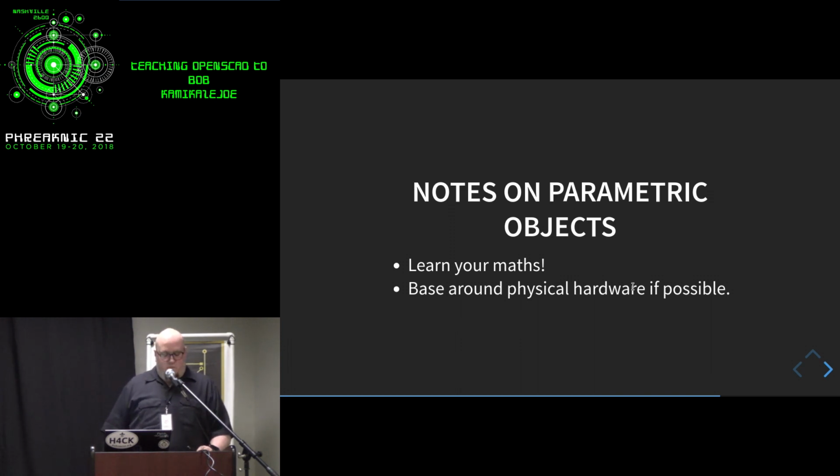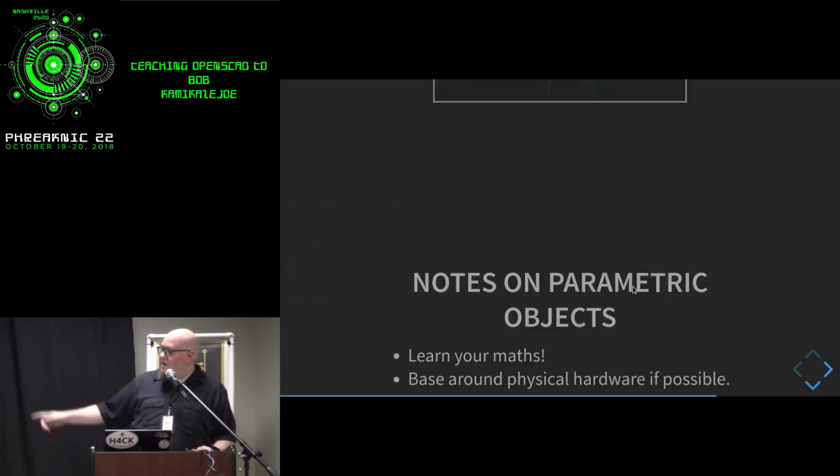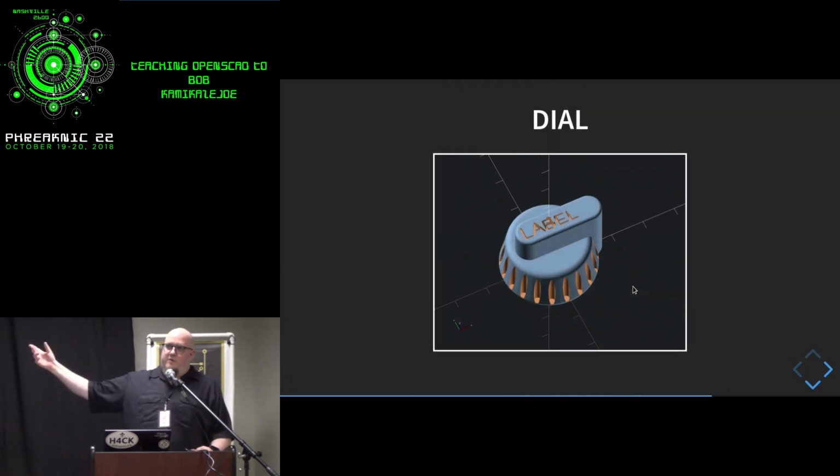But yeah, all these, go back. This is a screen capture, but this is what I see in OpenSCAD when I'm writing code. Every time I make a change, it live updates a kind of rough outline. And then you can hit render and get a more proper version of what the final object will be. So sometimes you'll see artifacts that once you render won't be there. But yes, is the short answer to your question.